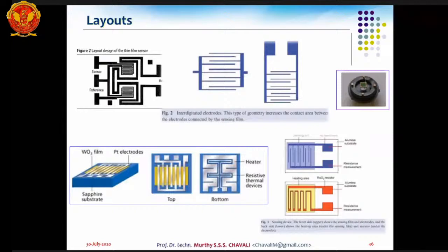And during those early days, most of the gas sensors responded at high temperature. That means you need to have a second circuit beneath the alumina substrate, which is for heating. A single millivolt change in electricity is going to give a change in 100-degree temperature or so. So typically the platforms that we have used are covered with ruthenium oxide so that we get the required temperatures.